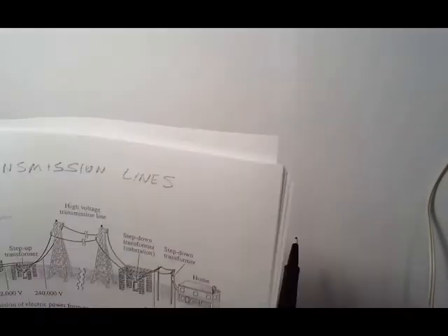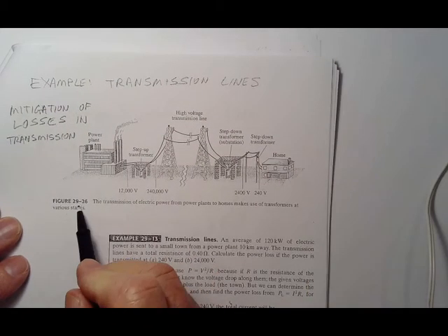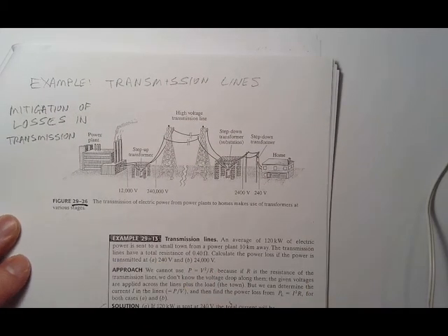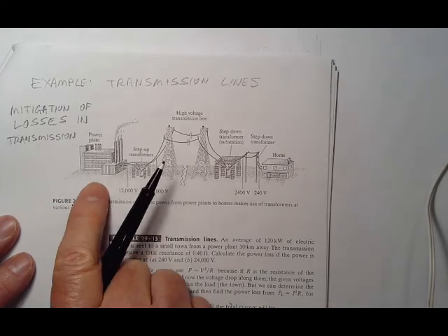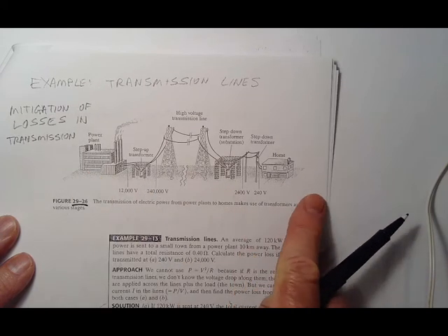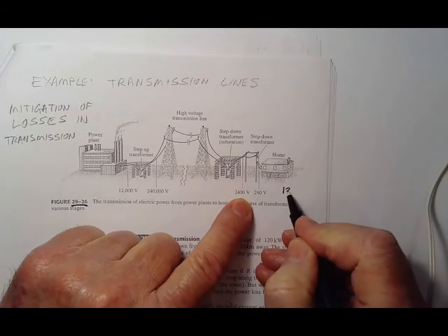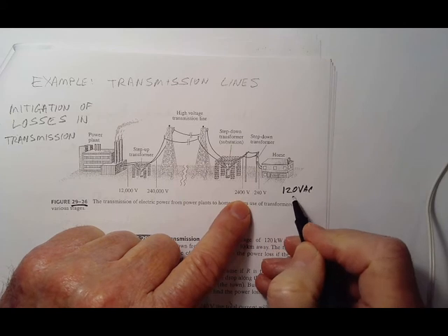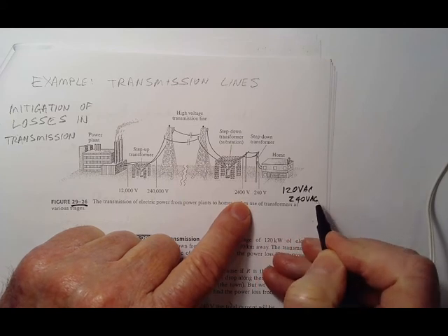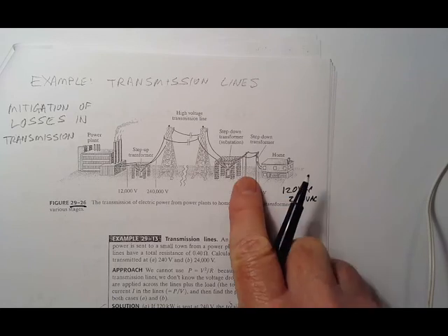Okay. Why do we care about these kinds of things? And why do we have transformers in the world? This is a very good example. This is example 29-26 in the textbook here. It shows you kind of starting from a great big power plant somewhere, a coal plant, a gas plant, a nuclear plant, starting from here and ending up in the house where you're sitting right now. In this house, we want 120 volts AC, or 240 volts AC. The outputs you have are 120 volts, but you have two phases, one up and one down, so it's really 240 volts.